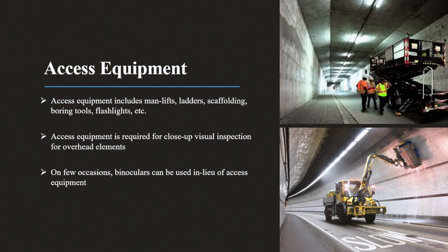Oh, this is just an access equipment. It's just to allow somebody to be in there, but that could be one thing. Or you can use a GPR attached to this one. I'm referring to the equipment itself. Sometimes you do this on a bridge, with a human being inside, or you can attach a GPR on it, and then you end up scanning the lining of the tunnel, and that can tell you if you have cracks or voids, or if you have a water leak.